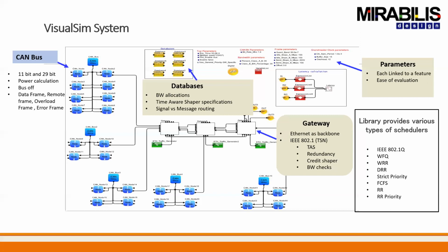So that way, for example, I want to run a scenario where I've got multiple CDTs, or multiple CDT slots, and I have signals versus messaging. How does that routing get impacted as a result of the decisions that I'm making at the routing table level, or at the slot level, or at the buffer level? How does that impact my end-to-end latency?